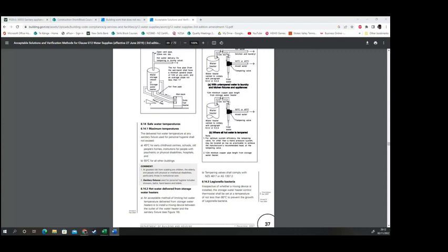So if you were to say, under building code G12, section 6.4 or 6.14, that's your reference, and then you just say the temperature that it should be set to. Okay, you'll be fine. Then he talks about potentially an untempered supply. Okay, it's too cold. You've got to think a little bit, why would it be too cold? So this is all actually linked to the same scenario question at the retirement home. So why would he have it cold and the other one's hot? You've got to come up with a reasonable solution.